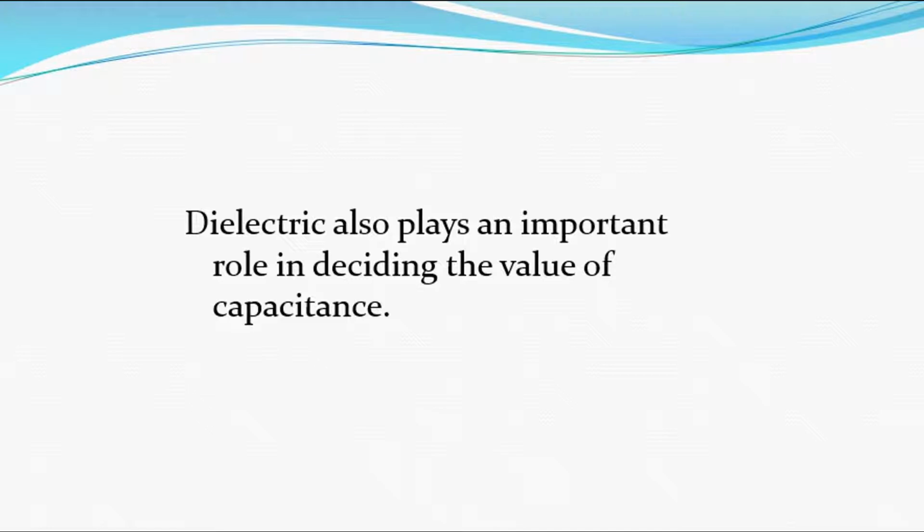And after that, you also consider the tolerance and the ripple current. Numerous things need to be considered if you are to take on a capacitor. So in this case, dielectric plays an important role in deciding the value of capacitance of a capacitor.